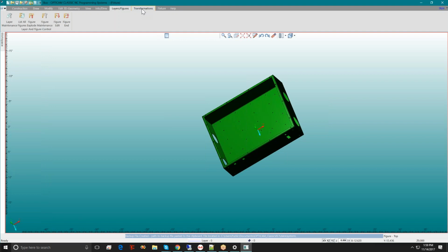Basically on the transformation menu, it's typical what we were doing before. Basically, copy translate something. You might need to do two steps on a fixture. You might have to do some tack welding on one part of the fixture, and then move it to a second station and do the rest of the welding. So you might want to copy or duplicate the solid bits, the parts, so you can remove the ones you don't want in the first step because they're subsequent to the second operation. So you can use copy translate to do that before you start doing the fixture design, as it were. But that's really it. You can mirror stuff here. You can translate, scale stuff, whatever you want to do.